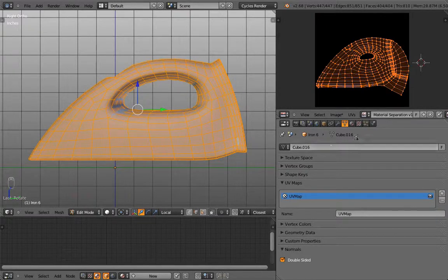And you see now here inside the mesh data, we also have something called UV map. So what does UV map really mean? Well, the problem all programs have is they're representing complex three-dimensional surfaces. And how should the software know how to put a text or an image perfectly over it? So for that you have to, like we did, unfold it, make it flat. And UV, think about it like X and Y, it is a coordinate system.